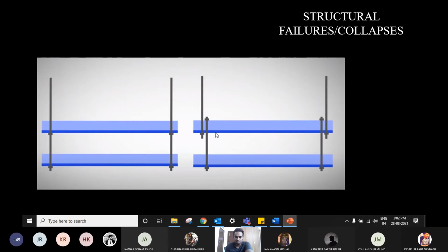Okay, load number 1. Second thing is this walkway, like the fourth floor walkway, is also directly transferred through this particular nut. So this connection over here is experiencing twice the force than it is actually designed for. In case A, you have the upper walkway sitting. Your tie rod can take it. Now the tie rod did not fail. Your hanging rod did not fail.